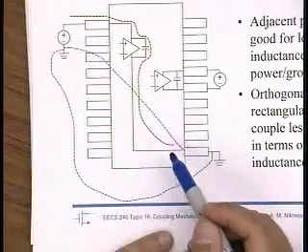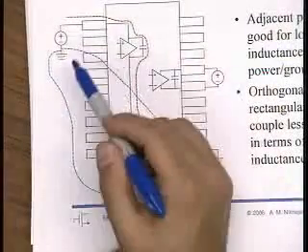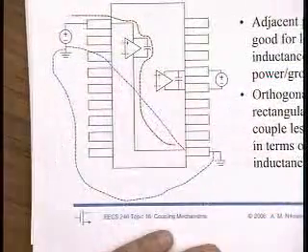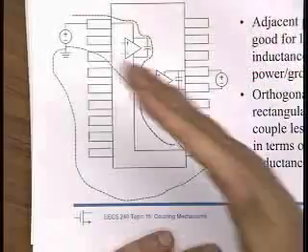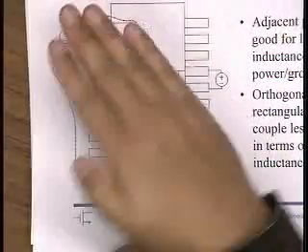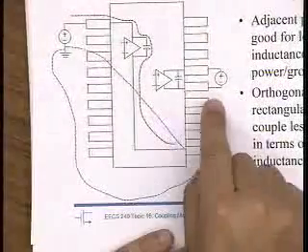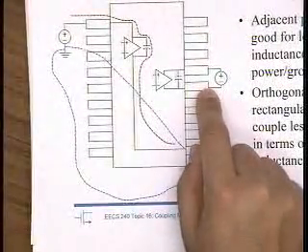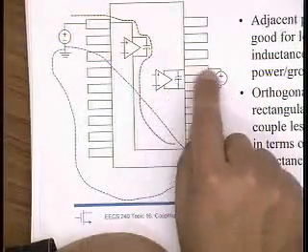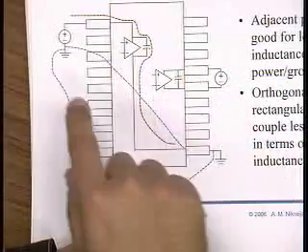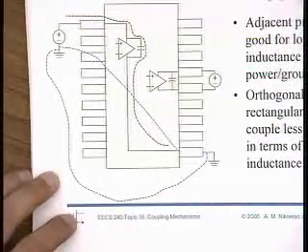But you can see that in either case, there's a huge loop here. In the case that it's on board, we're really screwed. We got this huge loop. In the case that it flows on the ground plane, it's a little bit better. It's more of a vertical inductor, so now the inductor is defined in this plane. In this case, it's defined in this plane. But why did we do that? If we had just used two adjacent pins for VDD and ground, you could see that the loop is very tiny, and this loop has very little inductance compared to this huge loop here. Okay? Questions or comments about that?